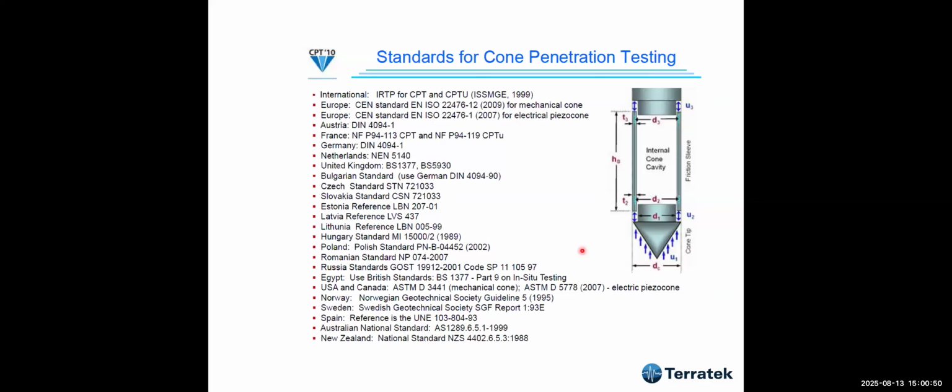There are many standards around the world. The ASTM standard here is very good. One for the electric cone, ASTM D5778. But there are other standards. Wherever you go, there's some difference. But the American standard is a good one.